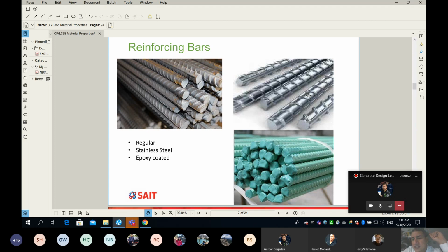This project uses stainless steel. It was the Heritage Bridge in South Calgary over the C-Train, because those bridges are supposed to stay for 200 years, and building them with normal rebar is not a good idea, because they get rain the entire year. There is lots of moisture, and so they built with stainless steel. Only one project, because it is very, very expensive. But it looks beautiful, by the way.